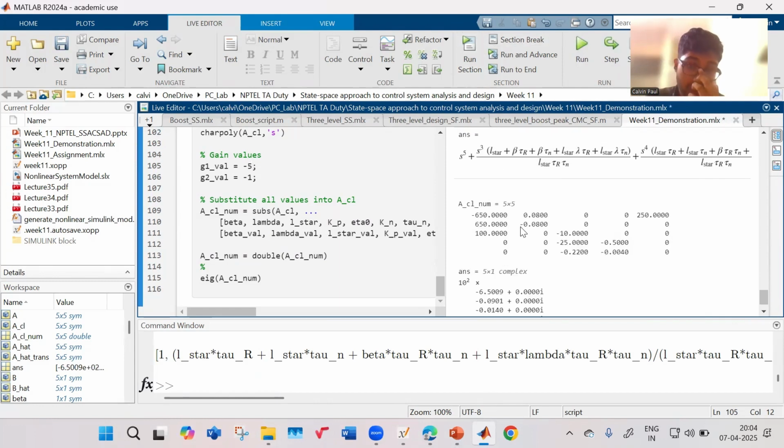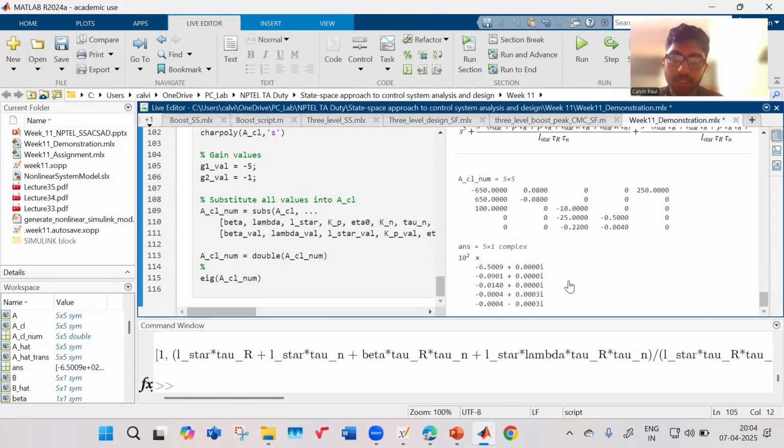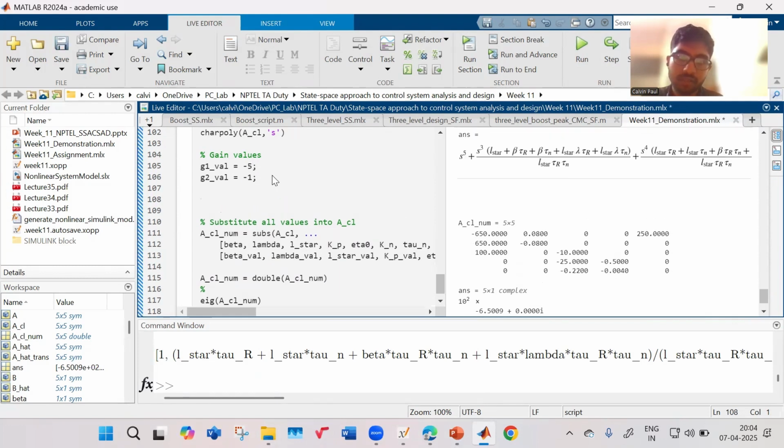So when G1, G2 are positive, it is not possible to stabilize it. We need negative feedback. Probably this is the consideration for the need for negative feedback, and the positive feedback is becoming unstable. But probably a thorough analysis of the locus of the pole locations will be required to check exactly.